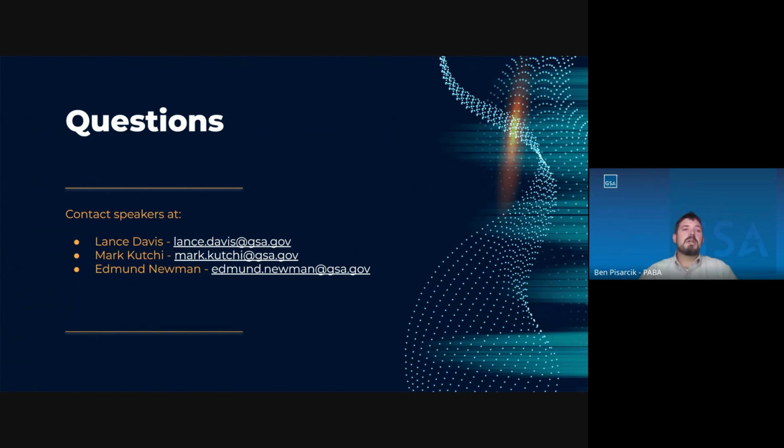Speaking from my perspective, there's also another question here about a fire alarm system. I would say you would demo all that cabling and conduit for the entire fire alarm system, because that would be your scope of work. The mention of the mechanical pipe and the mechanical space is kind of a limited case situation, but if you're removing electrical circuits, feeders, things like that, then it should all be demoed. Therefore, there would be no documentation. If for some reason it could not be removed, and this is not in P100, it would be great to document that for further use.